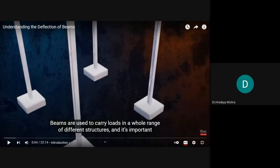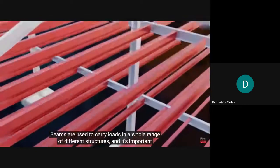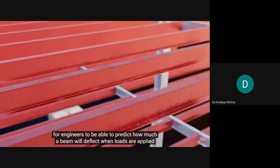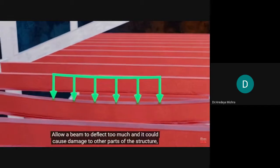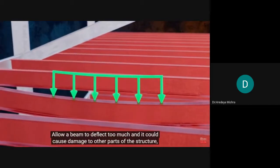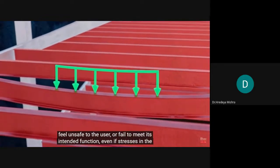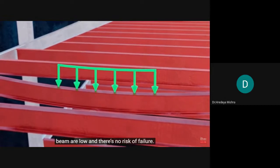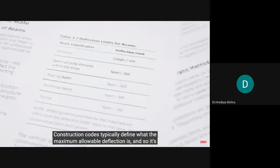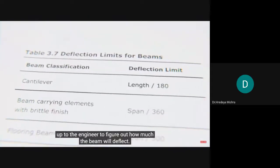deflection of the beam. Beams carry loads in a whole range of different structures, and it's important for engineers to be able to predict how much a beam will deflect when loads are applied to it. Allow a beam to deflect too much, and it could cause damage to other parts of the structure, feel unsafe to the user, or fail to meet its intended function, even if stresses in the beam are low and there's no risk of failure. Construction codes typically define the maximum allowable deflection, and so it's up to the engineer to figure out how much the beam will deflect.